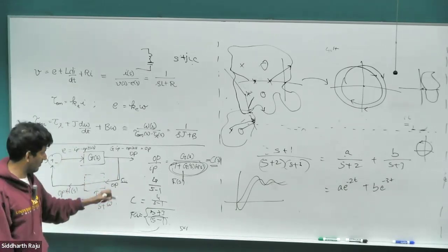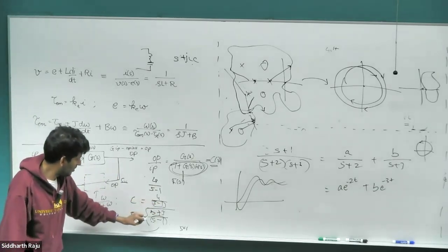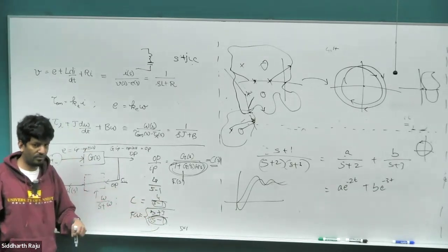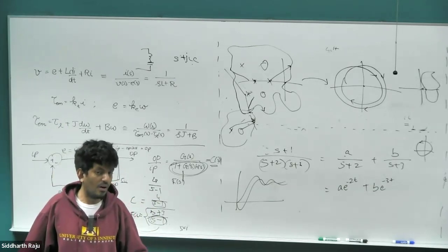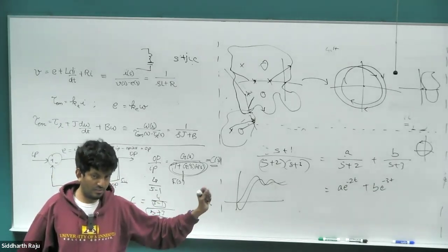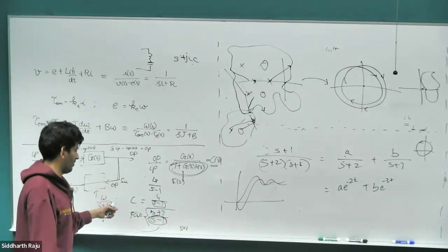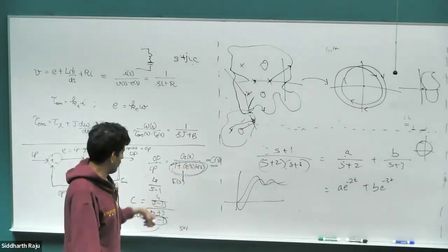Okay, it's going to be the same as the poles of the open loop transfer function. Yep, sure. Is that always the case or only for a constant value of H of S? Only for H value being some gain, right? Yeah, some kind of constant. If the H had some other thing, then that would come into picture.